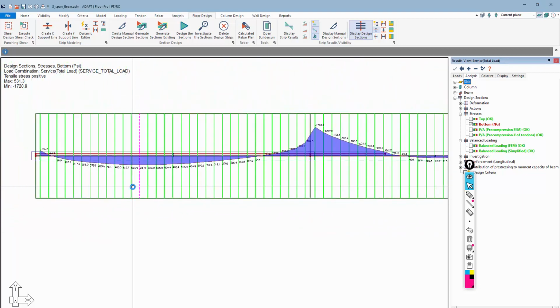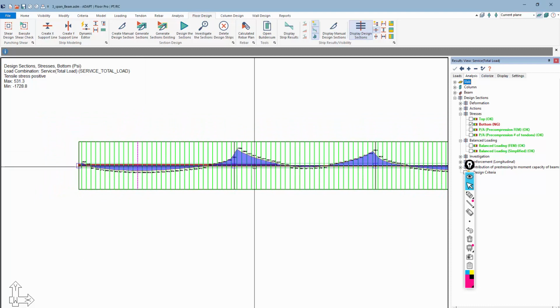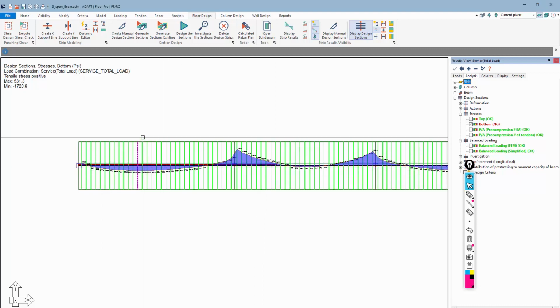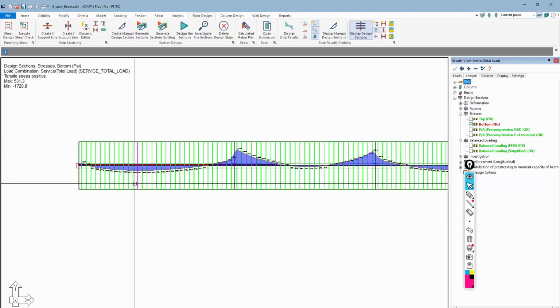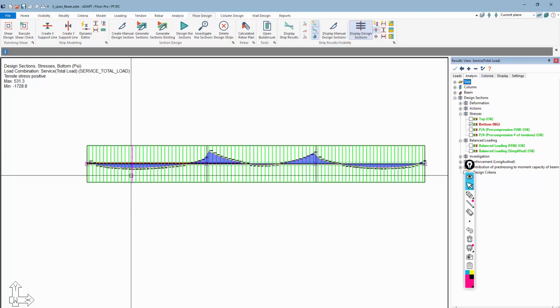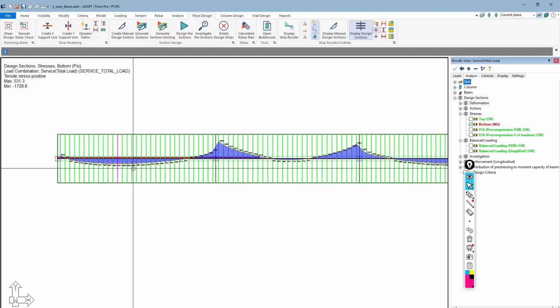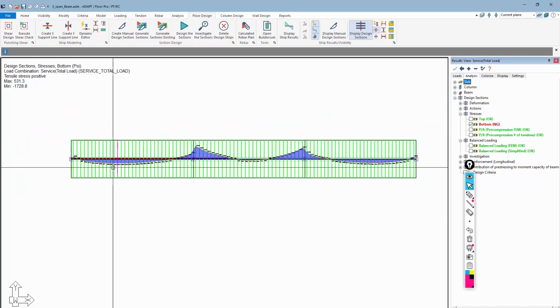So once we plug the tendons back into this model, what might happen is that this is a finite element model, so some of that load could shed. Depending on where it's anchored, we might get load shed away from the actual location that the program's integrating over, and you could get some variance between the optimizer and the actual finite element model. Sometimes it takes a couple of iterations to target and get down to where we need, but this is close enough. We'll say that that satisfies the design requirement. So that's just an example use of the optimizer.